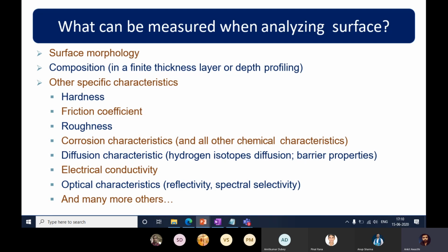And the second thing, which is obvious, is that we try to analyze the composition, what variation came in the composition. In my case, I performed laser heat treatment, and because of that oxides form, and these oxides play a major role in the color formation. So it's very obvious to get the composition of the oxides which are formed during the laser heat treatment, and that plays a very important role in getting an idea about what actually happened to the surface.